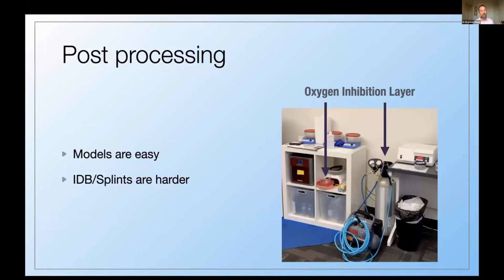But if you have a surface with a very high surface free energy, one of these materials that's really reactive, a lot of times what can help is that Dreve and some others, like Otoflash, actually have a nitrogen tank that you can hook up to the unit. So it actually flows nitrogen in before you hit the flash button. So you're actually devoiding the whole area of oxygen as it's flash curing. They tend to be pretty expensive, usually $4,000+.